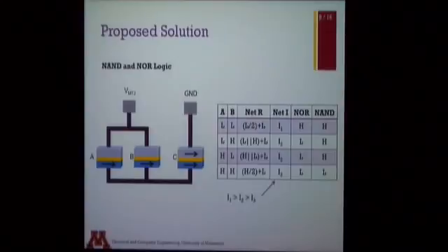What we know is that the relationship I1 greater than I2 greater than I3 exists in this particular circuit because of the values of these resistances. So if we can engineer the value of the applied voltage so that I1 is greater than IC greater than I2, then we are able to cut off the truth table at this particular point, and since I1 is greater than IC only for the first case, the current that flows from bottom to top writes a logic 1 to this particular MTJ.